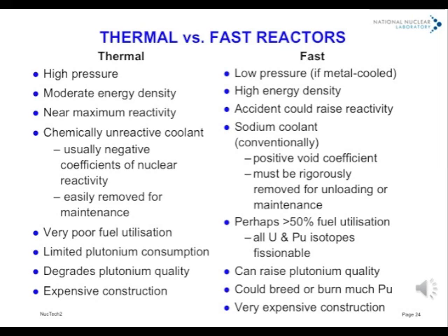Fast reactors capable of using this material do arouse some concerns on safety. The fuel configuration, unlike those in a thermal reactor, is not the most reactive possible, while the sodium coolant, although operating some 200 degrees below its boiling point and so needing no pressurization, has a positive void coefficient. That is, its loss could raise reactivity.